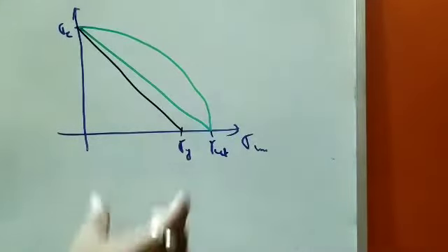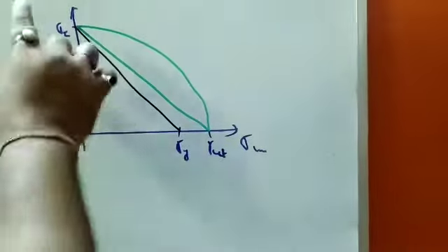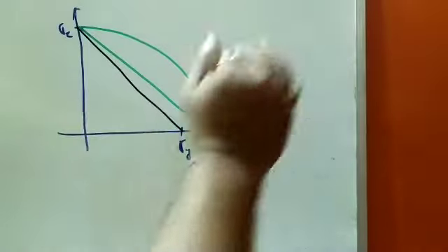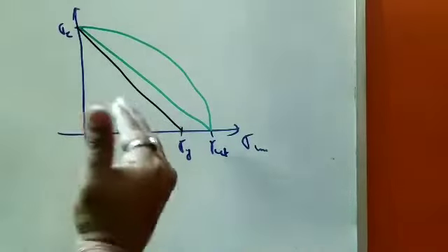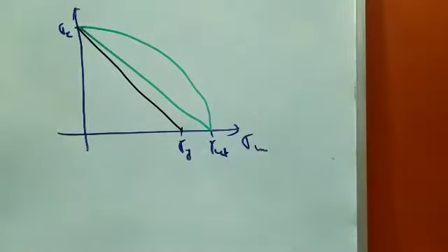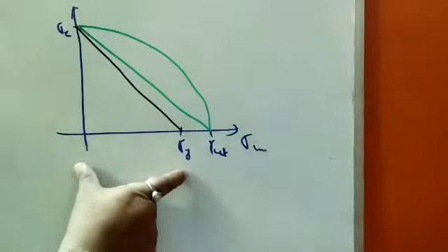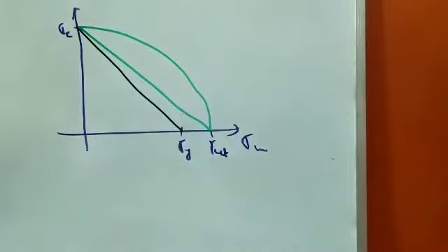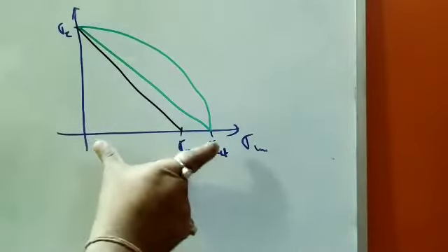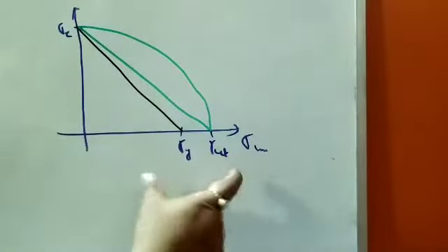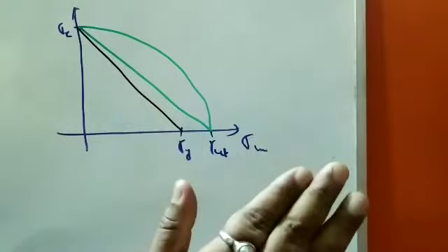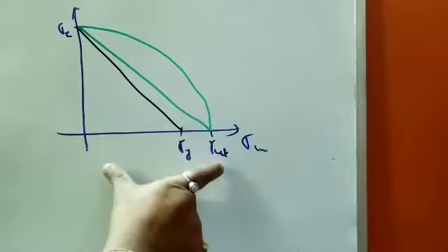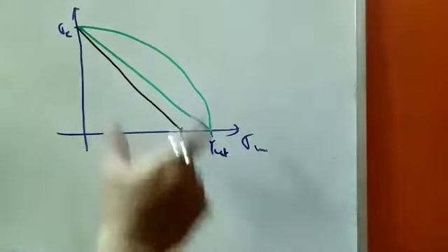One difference you could see is that if you consider the yield point and the endurance point, you could only go for ductile failures, because for brittle material there is no sharply defined yield point. So it is clear that Soderberg criteria can only apply for ductile material. For brittle material, for brittle failure, you have to go for Goodman criteria.